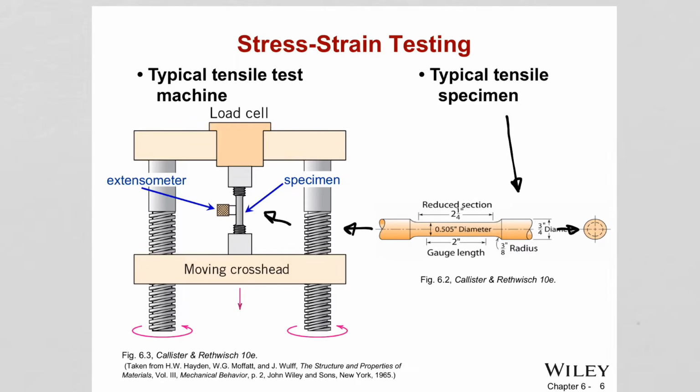device. The device will pull the part uniaxially in both directions. So the specimen is placed. There is an extensometer, which is a sensor detecting the deformation, because when we pull the material in both directions, the material will start to get longer, right? Extend or deform, or we call it strain. It's gonna change dimensions, and then the extensometer is able to measure that change.